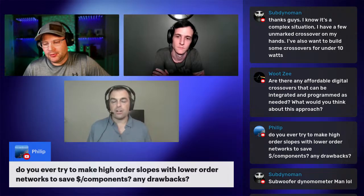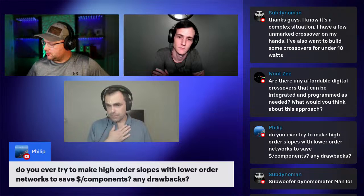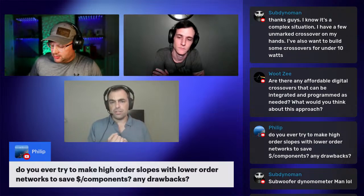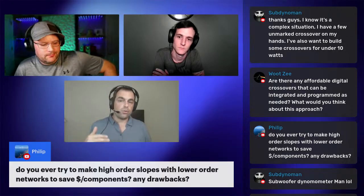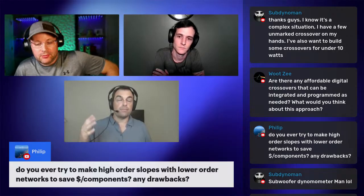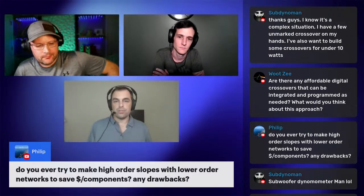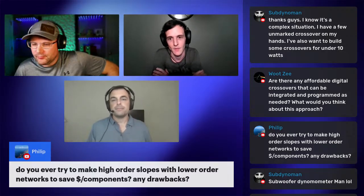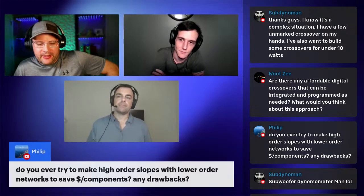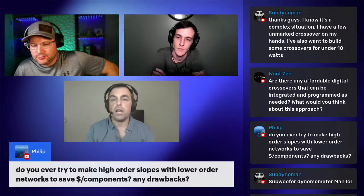This is what you're normally going to see. You're going to see this often, and a lot of my designs will be a single order filter on the tweeter, or maybe a second order filter on the tweeter, with a third or even a fourth order filter on the woofer, because the woofer tends to climb as you go up frequency response. So I need a sharper transfer function to get that thing into shape. Yep. So yeah, that does somewhat depend on where you cross over the tweeter at. That's absolutely a good point.